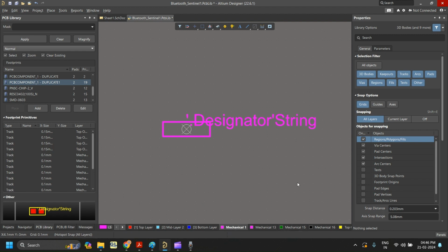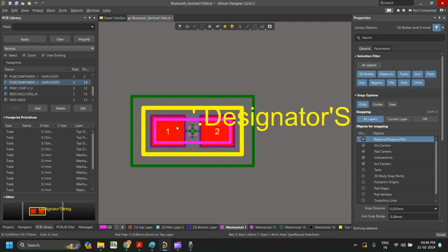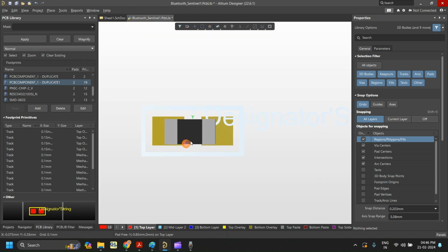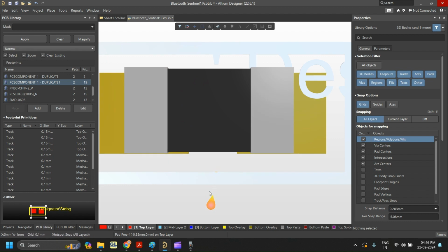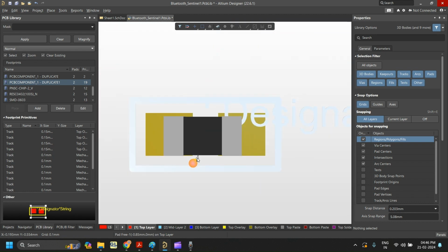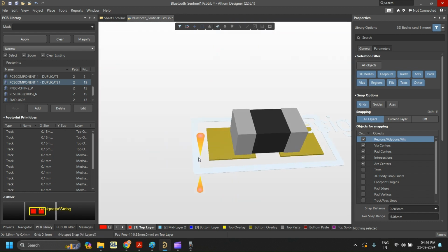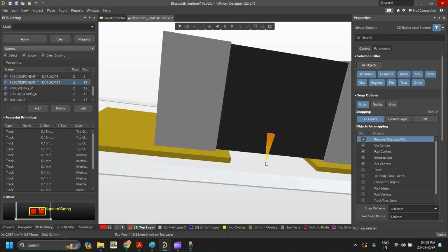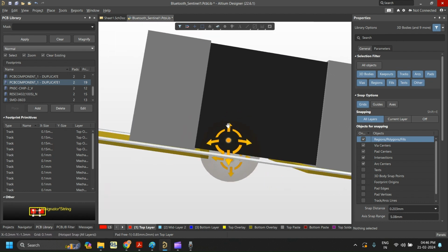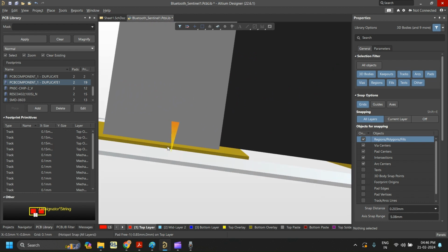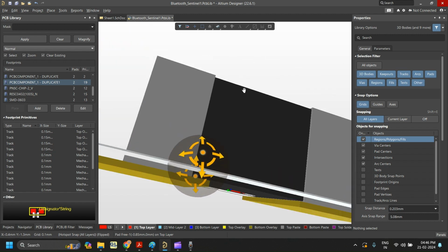Now again press Shift S to enable all layers. Now what thing did we miss here? We missed adjusting the 3D model. Press 3, you can see the 3D model here. Press Ctrl and right click to see like this, press Shift to tilt like this. You just need to check whether it is placed properly and the height and all is proper. So what we will do, a minimum 0.025 mm height gap you have to define. That and all is in advanced settings. Otherwise you can check whether it is properly sitting or not like this.